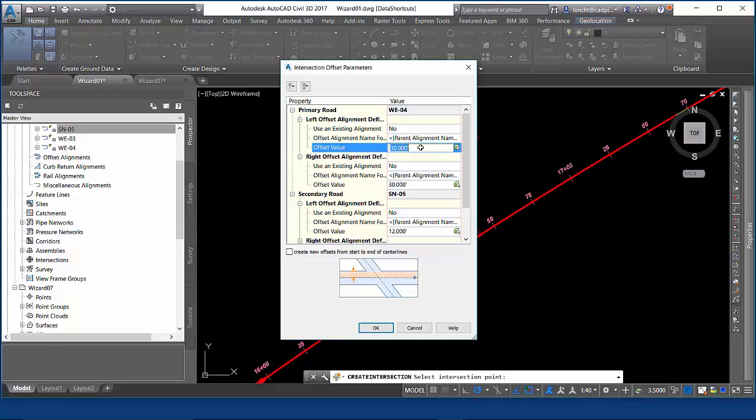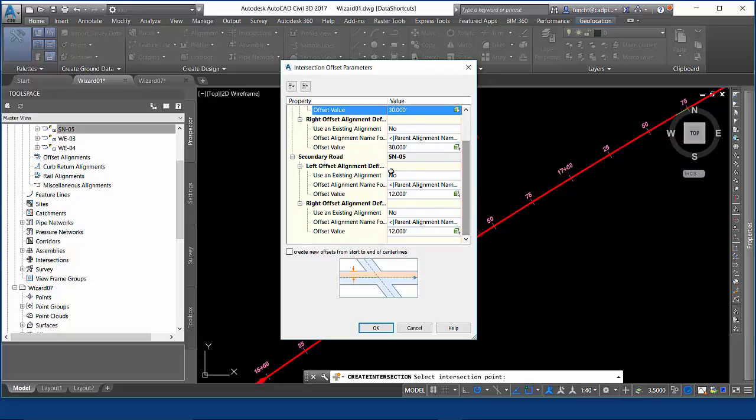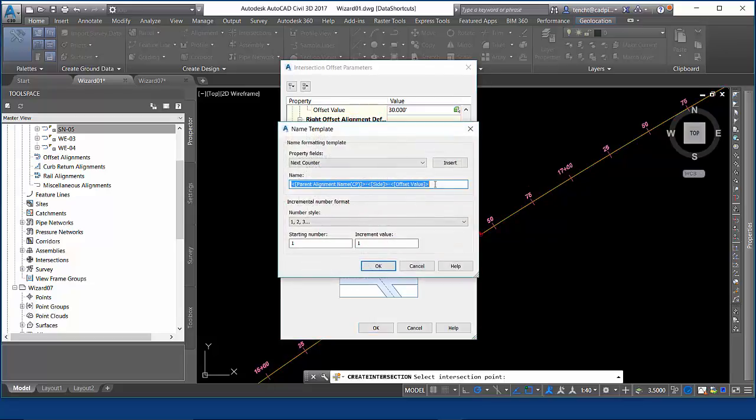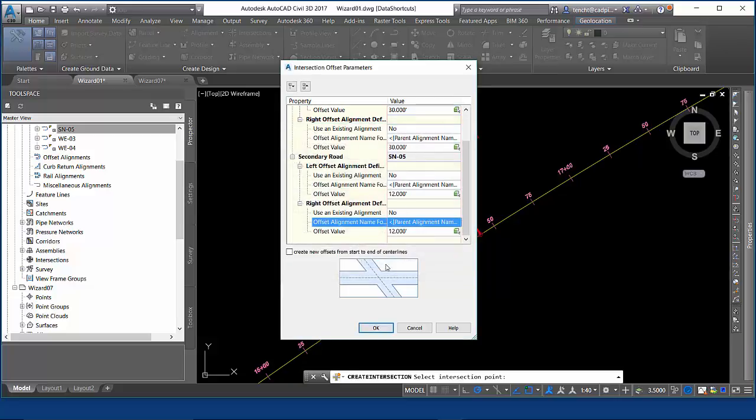This roadway is a multiple lane roadway, and we're going to use large offsets. For the secondary, the new road, south to north road, once again, we're going to remove those offset parameters from our name templates. Keep that stuff all straight, so I'm just doing lefts and rights to keep things simple here and not putting in that offset value, which I may want to change later. And these will leave at the stock AASHTO 12-foot level.